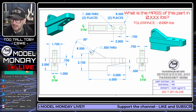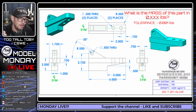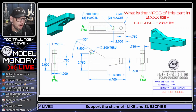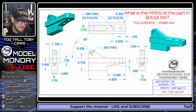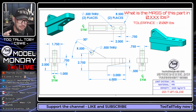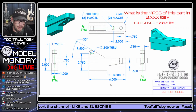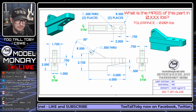But before I start modeling, I think that we should talk a little bit about what the game plan is, because anytime you are presented with a challenge, whether somebody gives you a 2D print or a napkin sketch, or even if it's just something that you see in your house and you want to design a 3D model, you always have to ask yourself the same questions. What is going to be my starting plane? What is going to be my starting profile? And for me, my strategy is always to keep my sketches simple. I don't want sketches that are too crazy and too difficult to work with. So I always try to keep my sketches simple.